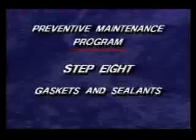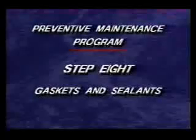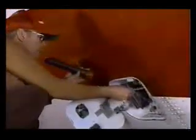Step 8 is inspection of gaskets and sealants. Gaskets and sealants are often used in aircraft construction to prevent the entry of water. If you spot any damaged or deteriorated gaskets or sealants on your aircraft, replace them at once to prevent water intrusion into corrosion-prone areas.